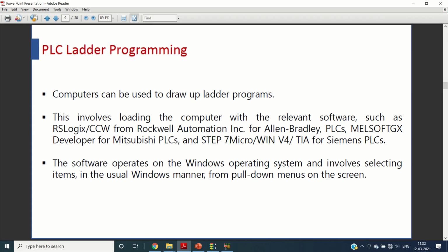Remember that the PLC should be in stopped condition while you are programming it. There is a simple software interlocking in the PLC, so that under no circumstances can you program a PLC when it is in running condition.